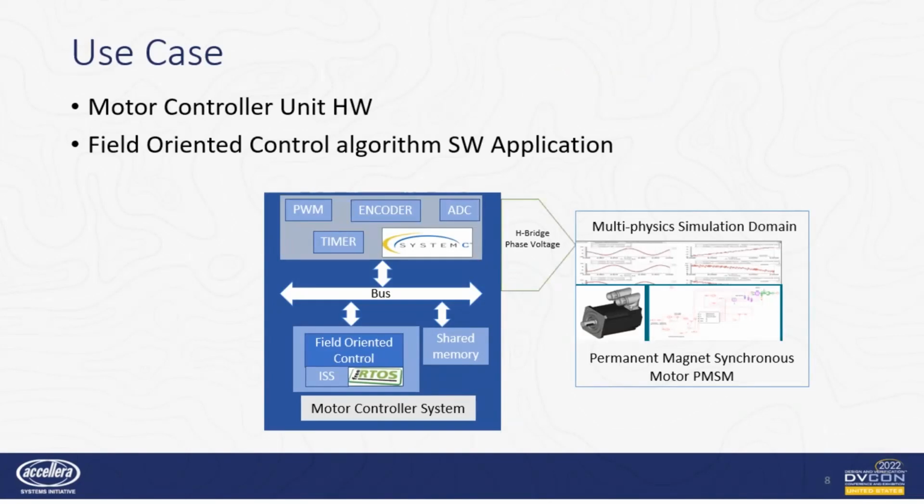Registers are mapped to the analog inputs that represent the motor shaft position and currents in the motor coil. These are used to monitor and sense the motor. This creates a feedback loop for the control application. Tight time interaction between the control software with the peripherals and external system components imposes real-time constraints on this system.